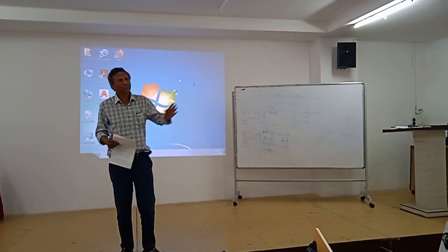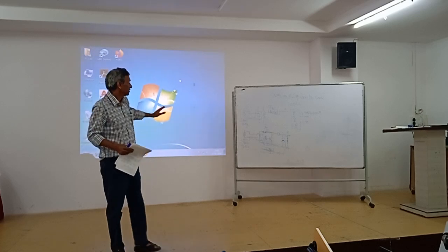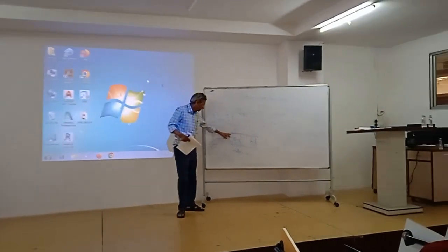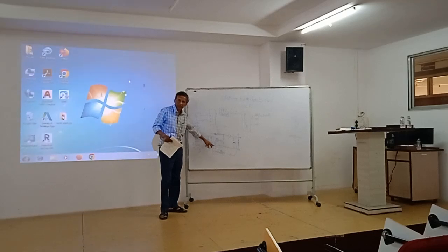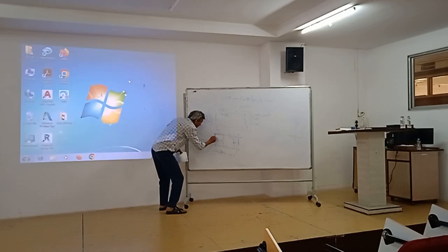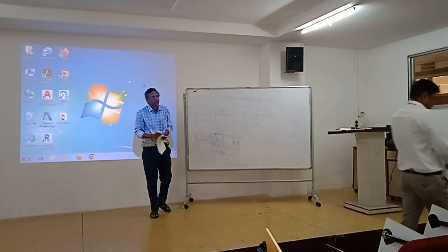By the way, PFC has multiple topologies. I am showing only one of them, the simplest. It has a few others also. So the capacitor is removed, and then I sense this current and this voltage. This current will also go to the controller.